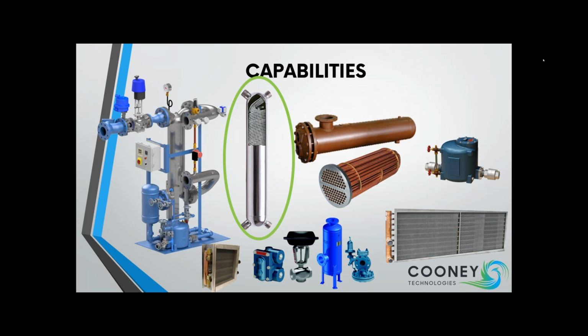For local people who are Veolia customers or any kind of district energy customer, they're sending out your steam with about 180 pounds pressure. They bring it into your building. It's up to you to take that steam and convert it to your hot water system or your domestic hot water system. And district energy usually doesn't take any condensate back. You have to get rid of your condensate on site.